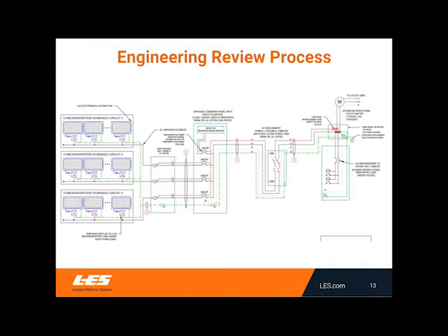The how is really what we get from the OneLine diagram. And this is usually where we have the most comments. We need to know where the system interconnect is and how it's being done. This is just a sample OneLine. I've got another one here too. In this case, the interconnect is done ahead of the main panel of the house. So we need to know specifically what the connection type in that situation is going to be because there's a tap ahead of any system protection. As the supply from LES comes to this meter, the closest upstream protection often is the fuse on the high side of a transformer. So there could be several neighbors connected to the same transformer.